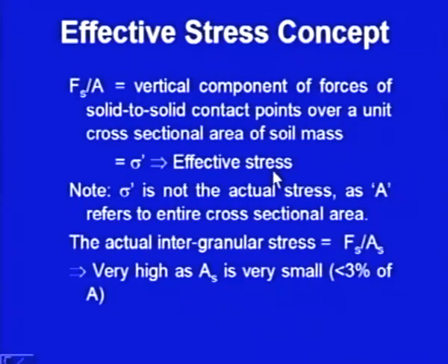Please note here that A is the total area, it is not the contact area. So, this sigma dash is equal to Fs upon A. If you are interested in finding out the actual intergranular stress, that should be equal to Fs divided by the actual contact area As.